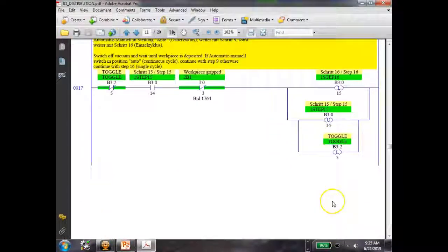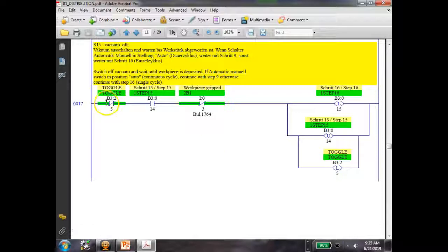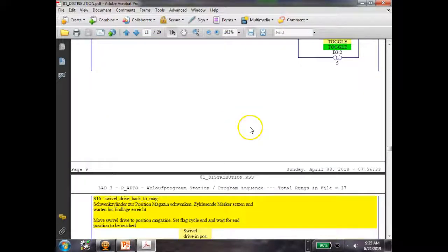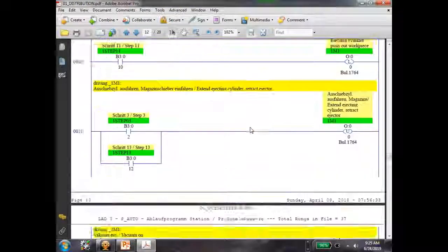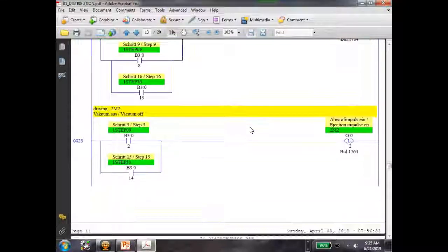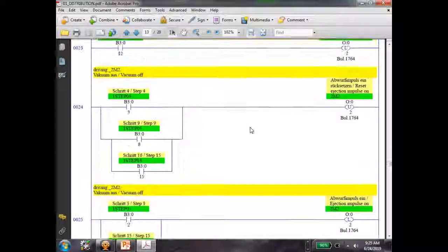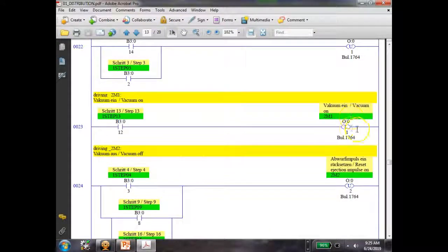So this is just sequencing through this thing, deciding if these sensors right here are true. That input right there is, and then eventually down here at the bottom of this, we'll get into actually outputs. So you can latch outputs. That's an output, but instead of using a regular output, they're latching that output, right? You understand that? So it's real popular in PLC programming.